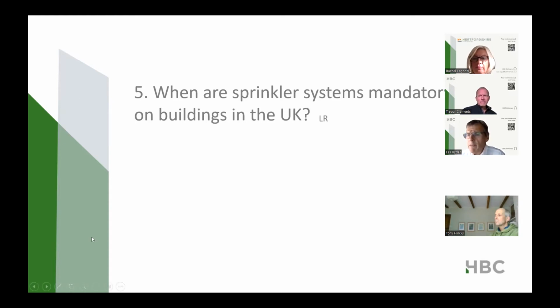Nobody is, and we've had probably 30, 40 applications in for buildings over 11 metres in the last year. Not one fire engineer or one developer said, oh no, we are going to design the building to BS 9991, and 9991 categorically says 30 metres. They've actually gone back to the ADB, which says 11 metres. One of the big problems we always had with people is, especially in this country, we're probably the only country in the world who's got two standards.